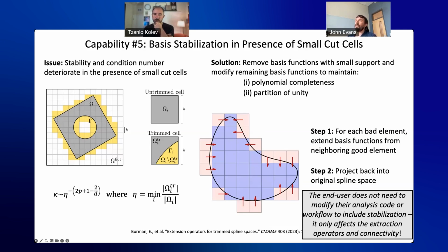That second approach is honestly the way I prefer to think about it. If you're thinking in terms of an element formation and assembly loop, after you've formed your elemental tangent or stiffness and force or residual vector, we then transform it into the desired basis and plop it into the appropriate place. In that approach, rather than forming big A first and then multiplying by M transpose and M, we are basically taking elemental matrices associated with A and plopping those into the appropriate place in big K.